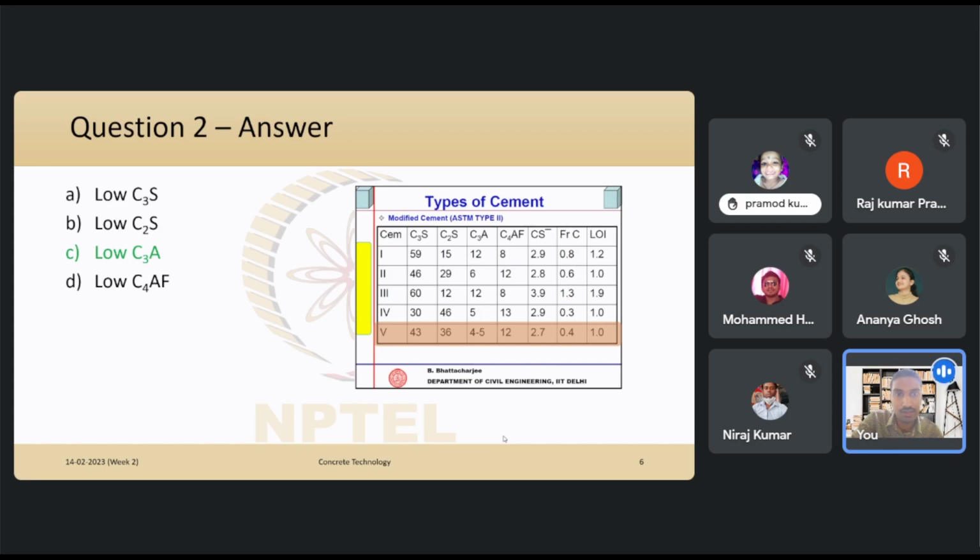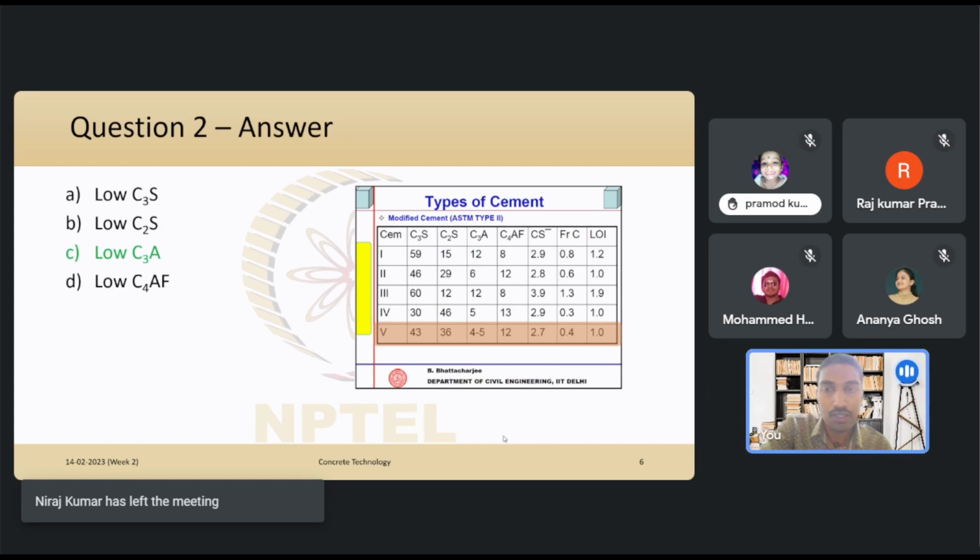When it reacts with calcium hydroxide, right? The problem with more formation of ettringite is that it leads to expansion of concrete, right? The volume will increase largely, so more tension is developed, and it leads to cracking of the concrete, right? To counter that, we reduce the amount of C3A present in the cement, so that this expansion or the sulfate attack can be prevented, right? That's why in sulfate resisting cements, we reduce the C3A amount.